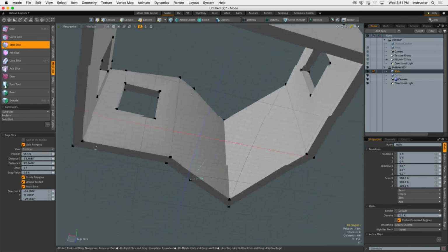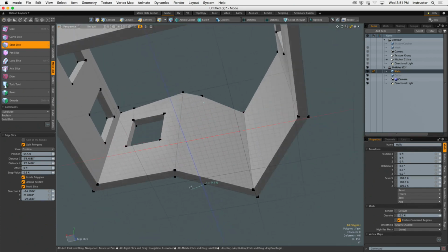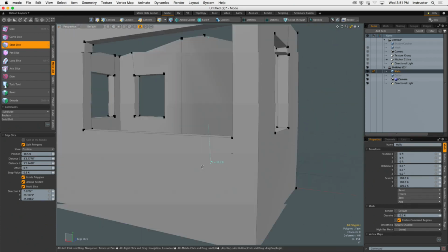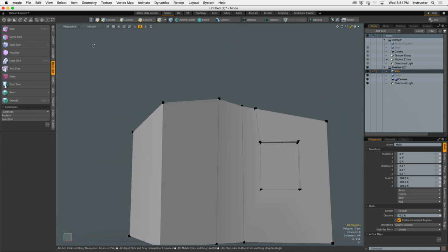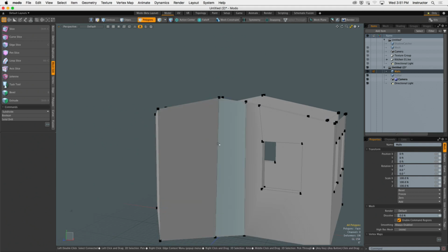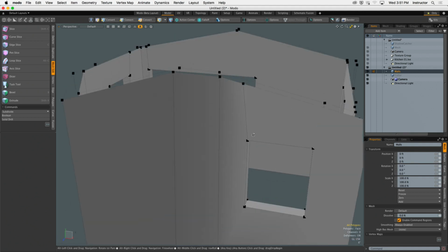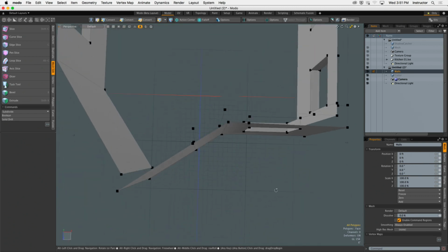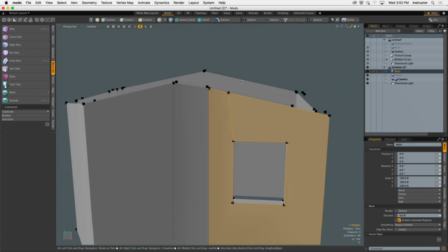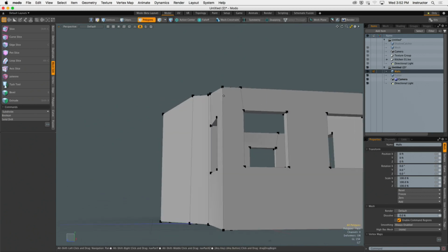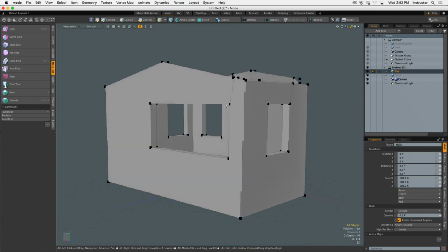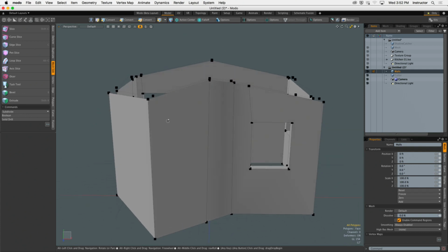Now I could slice all the way around, okay, like this, and then connect back up on its friend on that side. That works just fine. And now that shading error that we saw in the front is gone. These are n-gons over here as well, but because they're flat planar surfaces, we don't seem to get too many shading errors. Yeah, all this stuff looks generally okay, and I'm pretty happy.